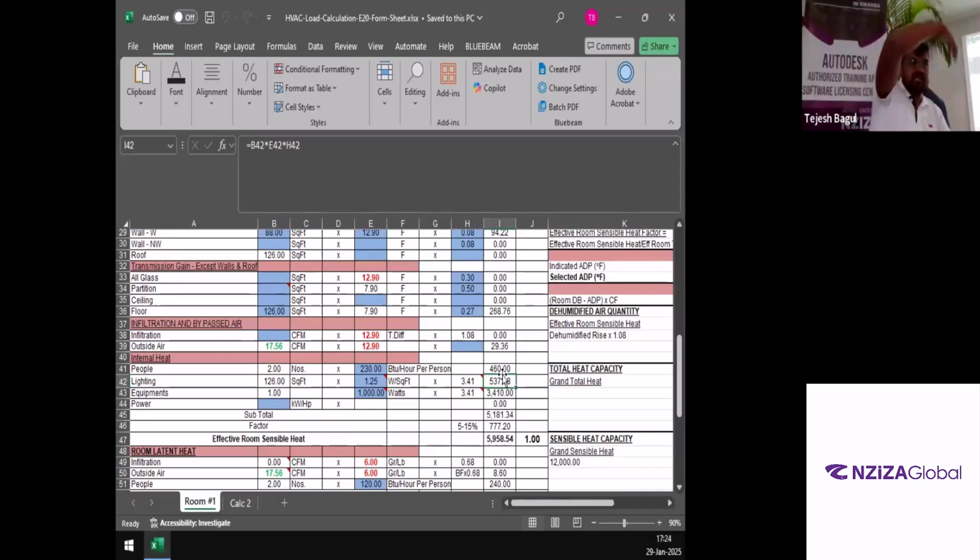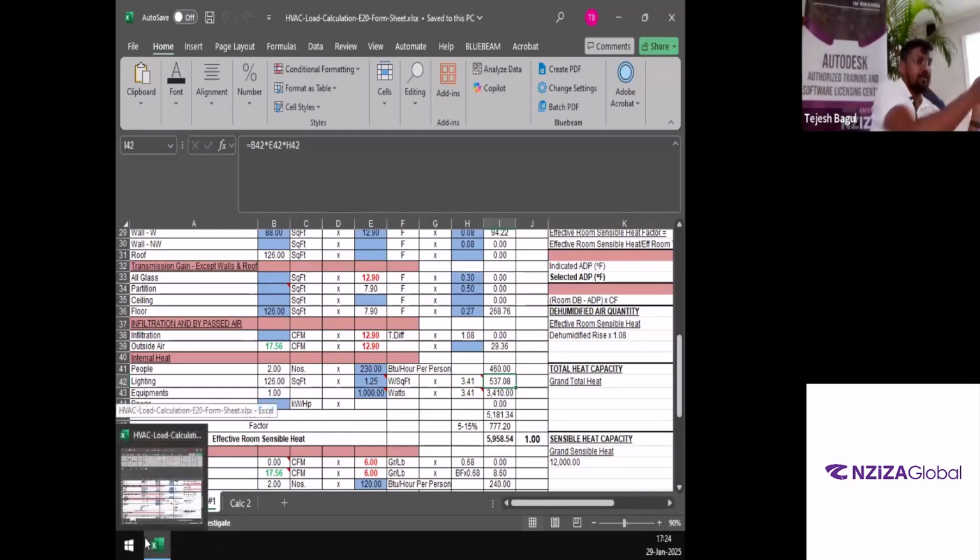Okay. In the yesteryears, we had to take that heat also into account to make sure our ACs can handle that heat. In that case, this watts per square foot was much higher, but now it has gotten lower. So in some cases, you will even find 0.5 watts per square foot. That is allowed. All right. Maybe for a small storage area, you don't get a lot of allowance over here. And this also you can get from the ASHRAE 90.1 standard. Okay. So again, I'll not jump deeply into it. I have shown it yesterday. The video is available, but that is where the wattage per square foot concept is coming from.